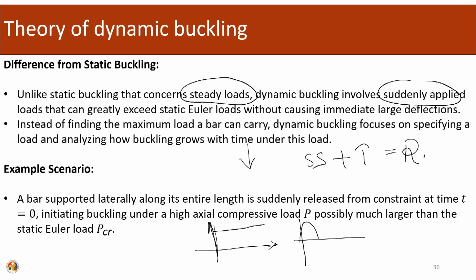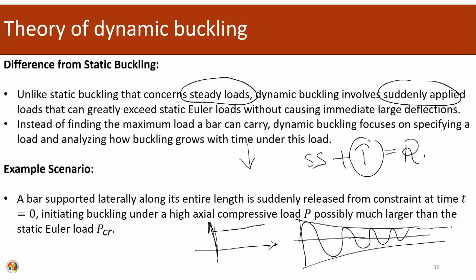And if we look over a great period of time, what we will see is that due to the damping and other effects, the transient effects die down. So, the only thing that remains is the steady state solution. This steady state solution we approximate as the static solution. In the static solution we also assume that the effect of inertia is not engaged. So, these are called the steady loadings. In dynamic loading, the transient effects are present for a longer duration of time.